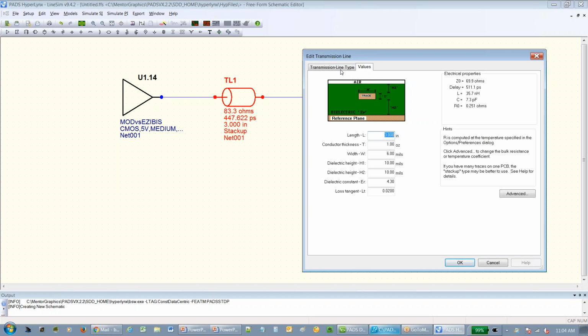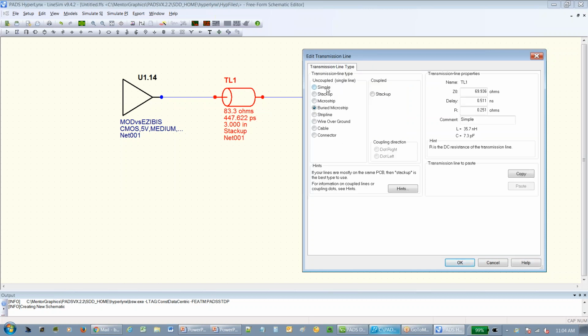Okay, so let's just play around. Let's just do a simple transmission line here. I'm going to set the impedance to something rather large. This would be if you're doing a 2-layer board, where there's no reference plane for your traces on the board, pretty much. So the impedance of your line is going to be quite high, and this is about what it averages, about 400 ohms typically.